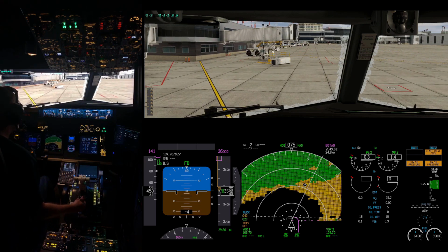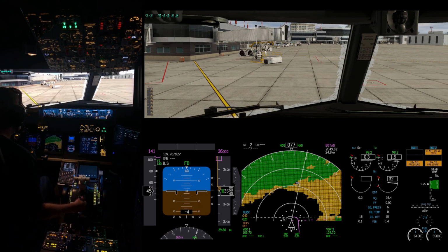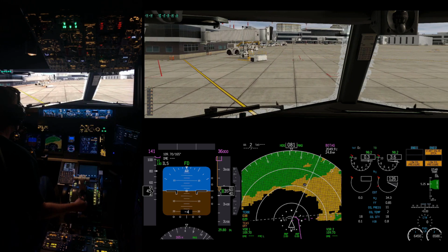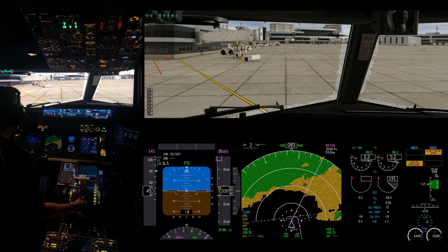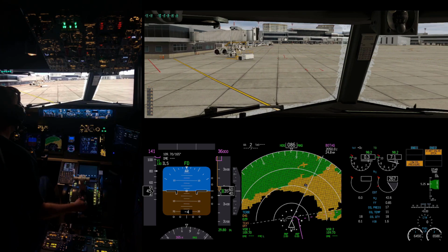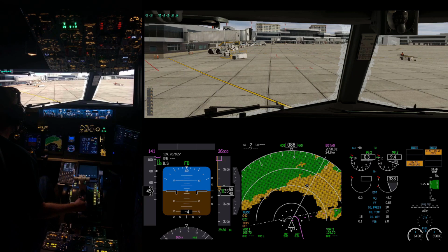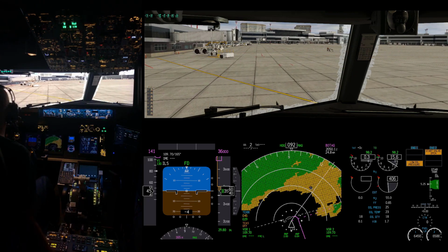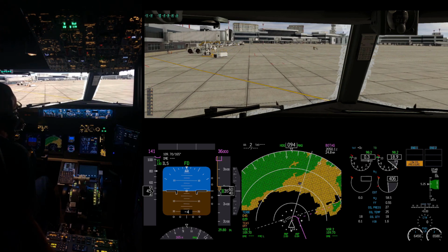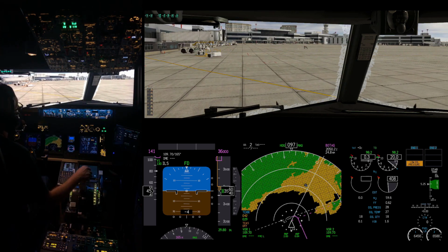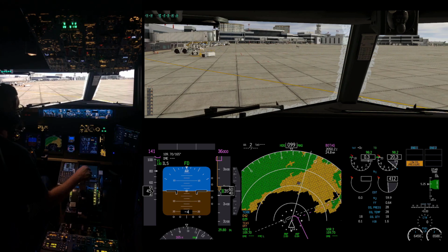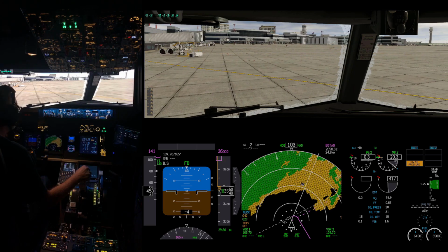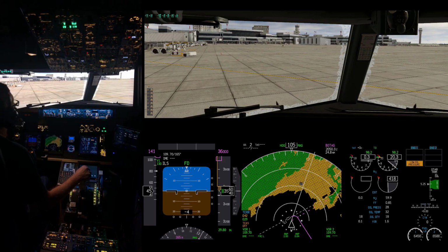We add fuel, and we have exhaust gas temperature coming up and N1 spinning up. And that was the engine start switch, automatically switching to off. So we look for stable engine, 246, looks we're good, so starting number 1.